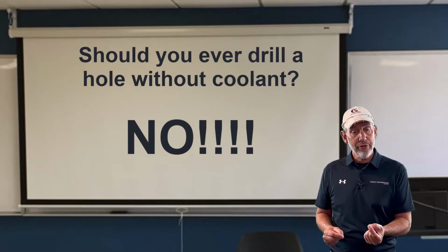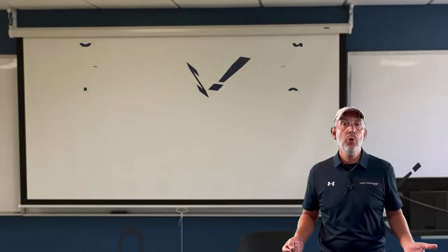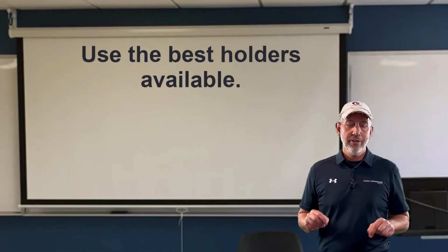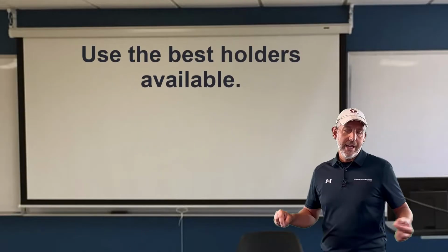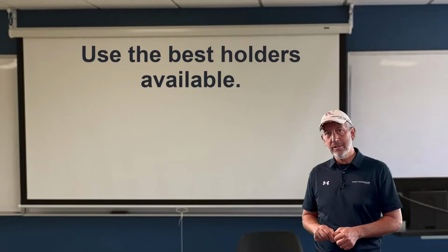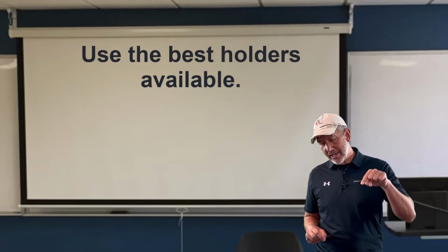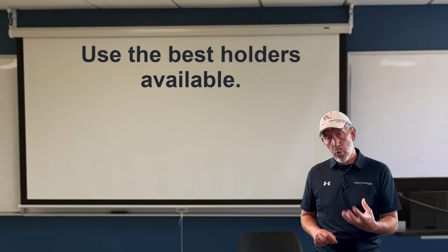Another big critical feature with a drill is TIR, run out. Make sure you have the right holder. The right holder with the drill is going to give you some critical advantages to actually drill a straight hole and a quality hole.